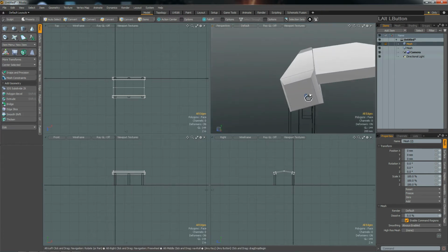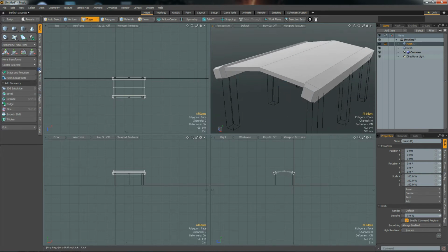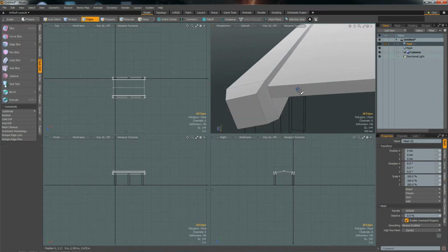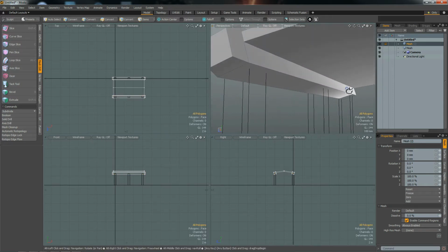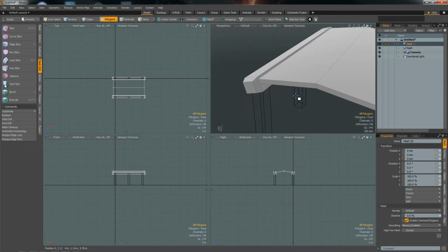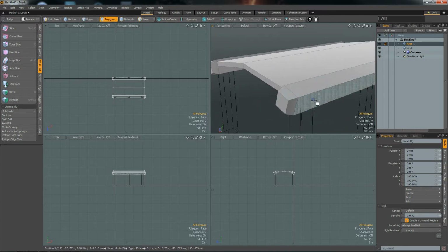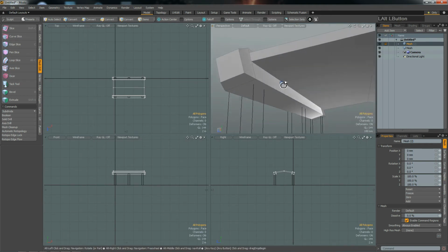So now that we have these things here, we do something that we should do in Modo on a frequent basis. It's called the mesh cleanup. Because when Modo does its operations, it doesn't really care about certain things such as normal values. You see the normal from this bottom face here looks rather strange. That's because if Modo would clean up the whole mesh every time you make a mesh operation, Modo would run super slow. So it keeps everything there in terms of geometry, but the rest gets messy pretty soon the more complex operations you perform.